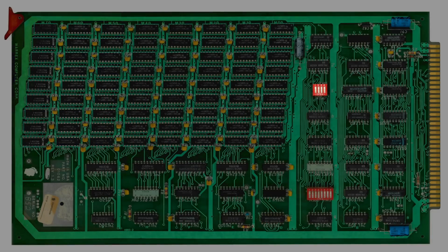This dip switch up here, though, is very interesting because it allows you to essentially roll which column of memory it starts with first. So this is how they're helping you diagnose where you have a memory problem. But there's 8 columns, and this dip switch has 4 positions.